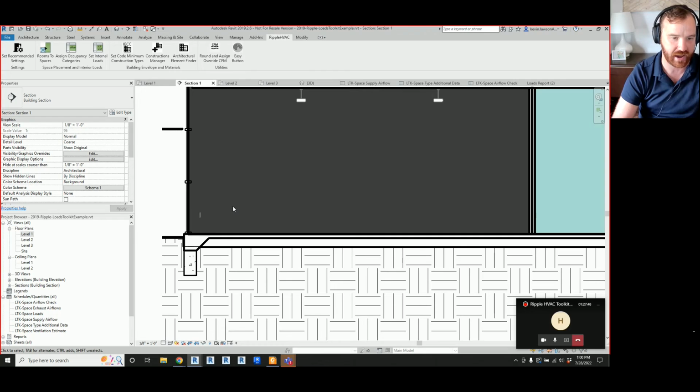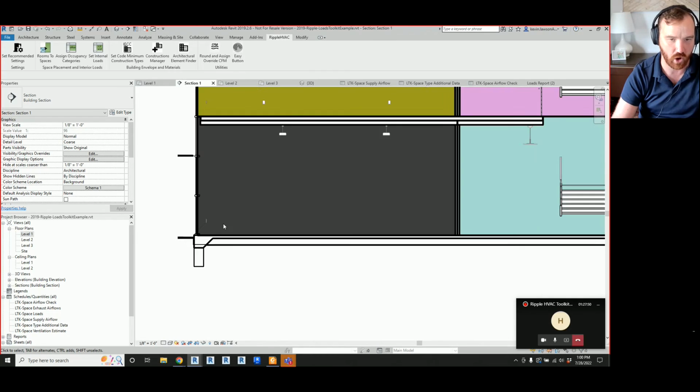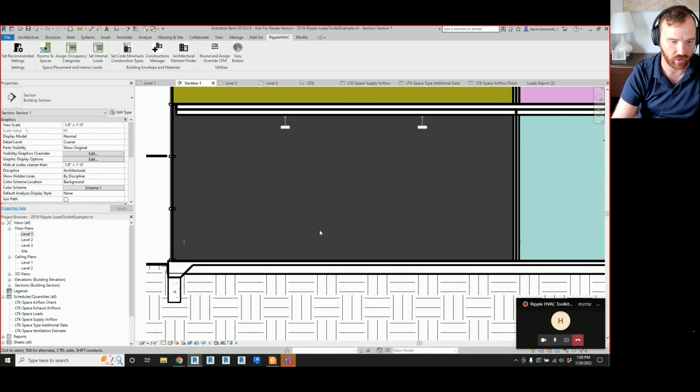Because I always assume no internal loads for heat loss through the slab, not only is this load going to be very small, but just the lighting load is going to be way more than any load that this can be. So as long as you're not taking credit for lighting in your heating load calculations, you really shouldn't be too concerned with the floor heat loss through the slab.